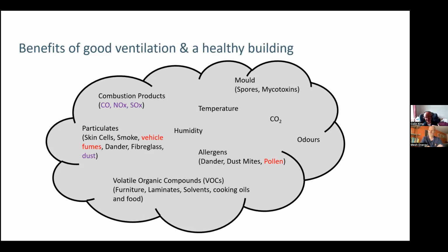But that accumulative moisture that always happens is in that one room, or everybody goes in one room because it's easier to heat one room. All of that vapor from breathing and living and activity then comes out of that open door and it migrates up the building. High pressure to low pressure will always go upstairs, into the bedrooms where we spend vast quantities of our time, which is where the mold then grows. But you don't see it straight away because mold can grow within 12 hours of the ideal conditions. And then it starts to become visible after 7 days. And then at the period of about 28 to 30 days, that's when it blooms and you get this visual appearance of the mold.